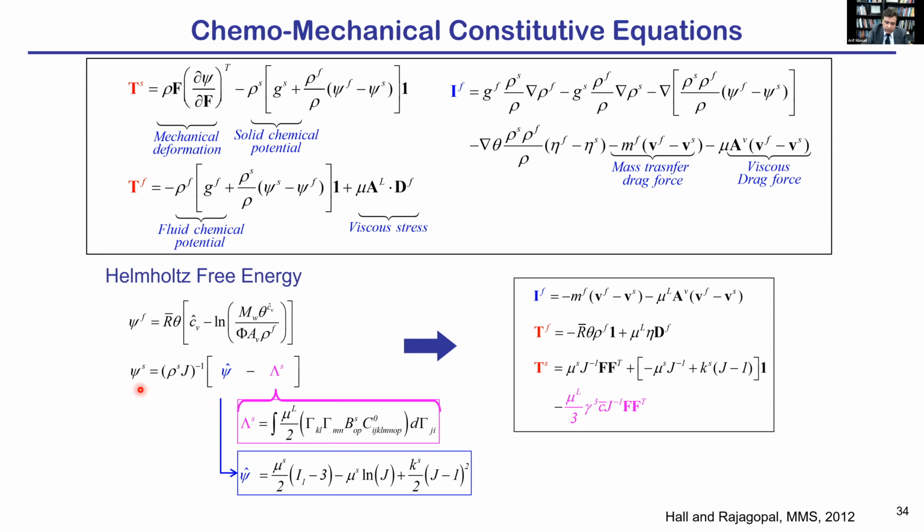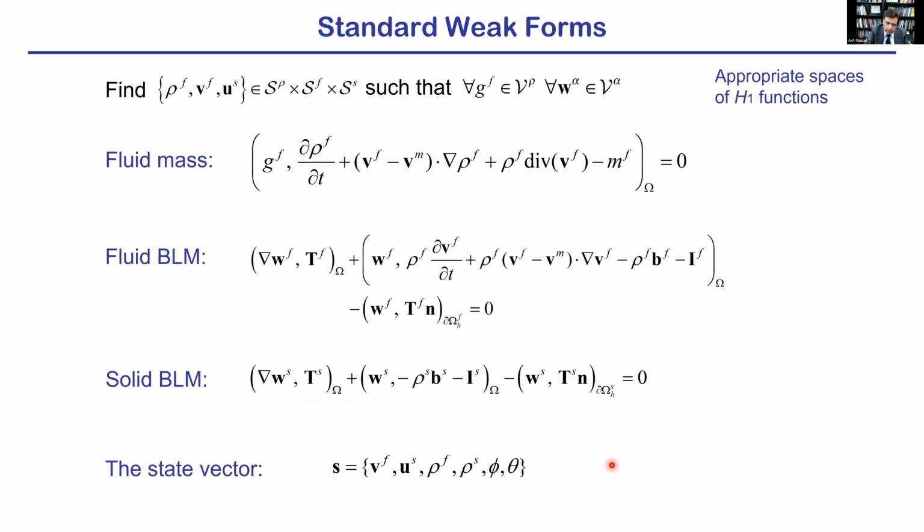When we plug these functions into these generic expressions, these are the expressions that we get for the interactive force field and for the stress tensors for the fluid and for the solid. And you can see that the finite deformation effects are fully accounted for in the stress evolution for the case of solids. So now let's look at the standard weak form for the balance equations, the governing laws.